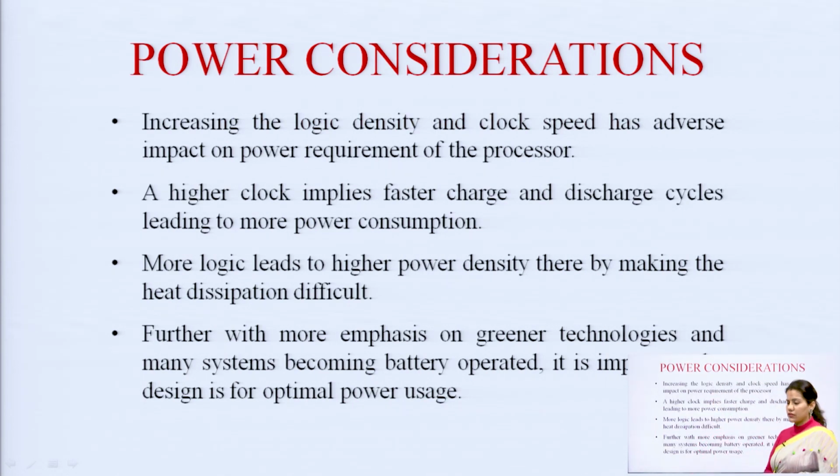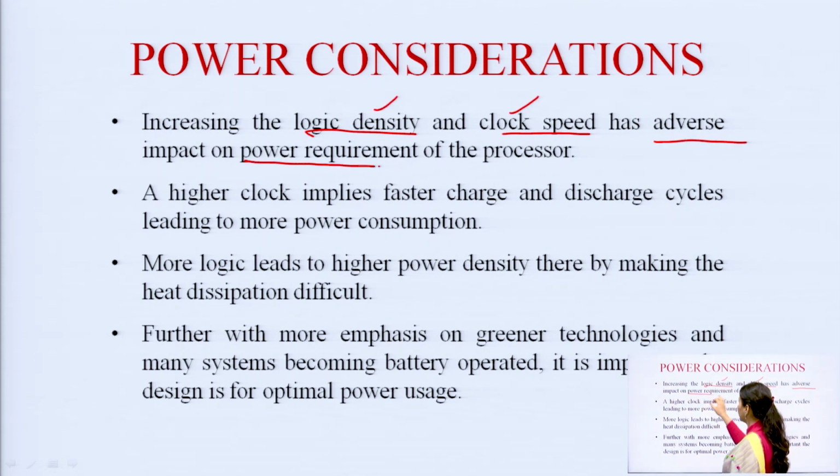Next is the power considerations. Power analysis is a very important feature when we are designing any VLSI application, or we can say when we are designing any embedded application. Increasing the logic density and clock speed, these two things have an adverse effect on power requirements. So, when we are focusing on more and more logic density and more and more clock speed, obviously we will require more power.